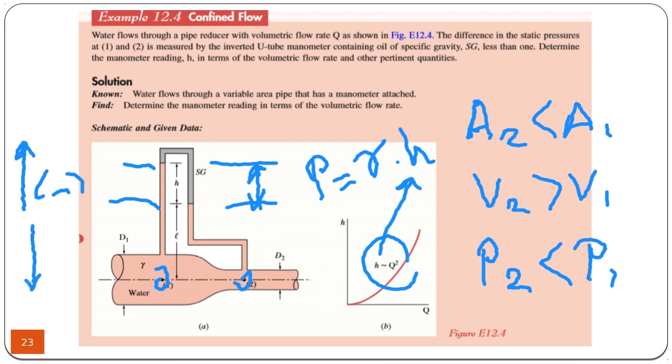So here, you go up the pink fluid, which has the total height of L plus H. Then you have an equal side here which cancels each other. Then you go down with this gray fluid with a plus sign, and you go down with the pink fluid with a minus sign again. So it seems that actually this part cancels that part.